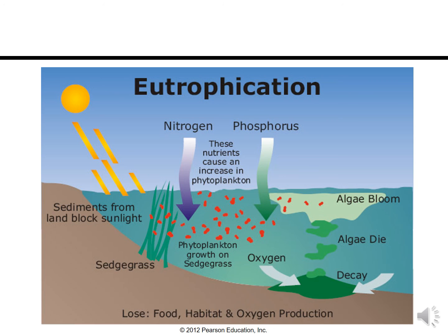That can cause problems for aquatic life, the animals or fish or any other water related organisms, which die because they don't have dissolved oxygen for their metabolic processes. So they are running out of oxygen and the sunlight is blocked, and then no photosynthesis, no oxygen. So biological oxygen demand increases because of eutrophication. Eutrophication is again the exponential growth of algae because of higher concentrations of nitrogen and phosphorus in the water.